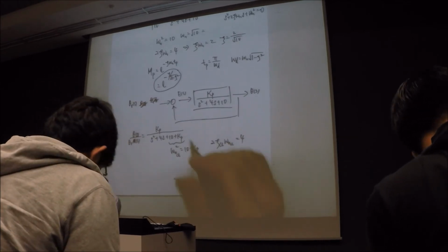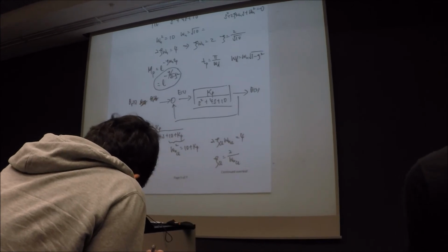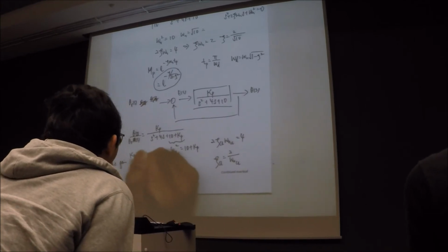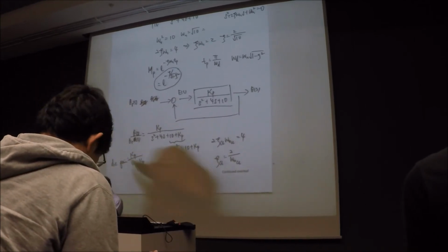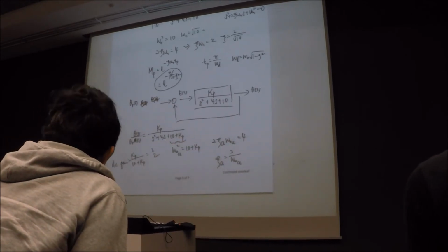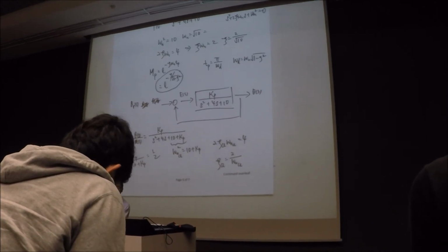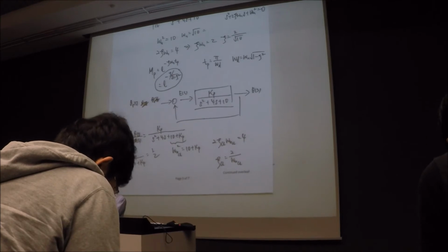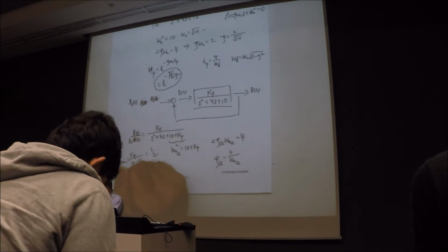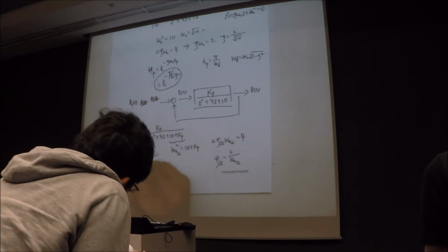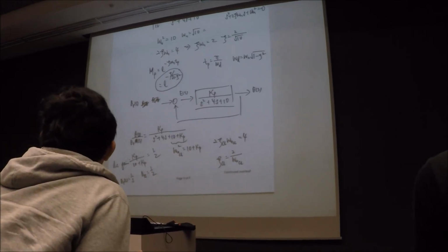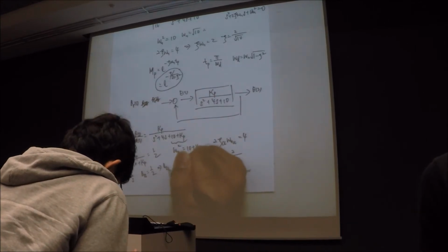So from this case here, what is your DC gain? DC gain is Kp divided by 10 plus Kp. Right? Kp is equal to 10, this is equal to half. So steady state error is 0.5, correct? Agree? Steady state error is 0.5 because your DC gain is equal to half. That means if your theta R(s) is equal to 1 over s, your theta SS is equal to half. As a result, your ESS is equal to half.